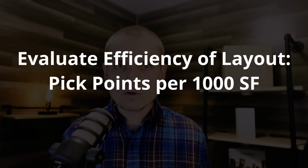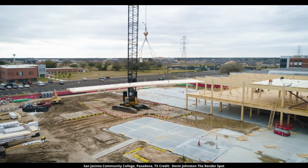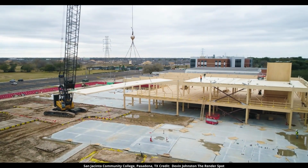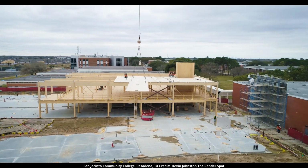So each beam is one pick point, each panel is one pick point, each column is one pick point. So by running the timber in one direction versus another, one grid scenario versus another, you can start to see maybe one layout has X number of pick points per 1,000 square feet. Another layout has X plus 3 pick points per 1,000 square feet.